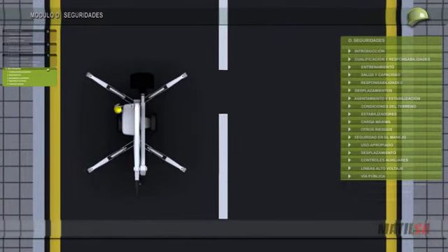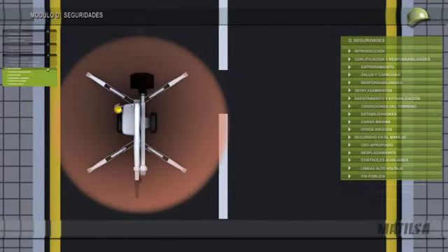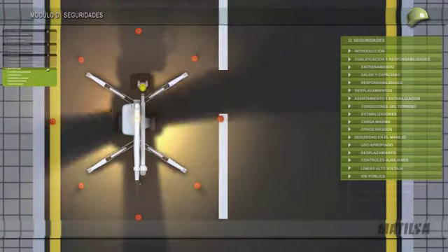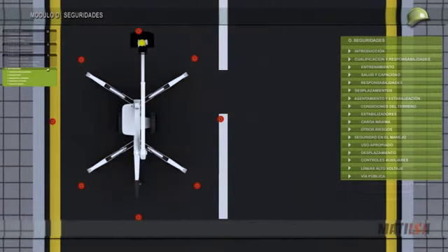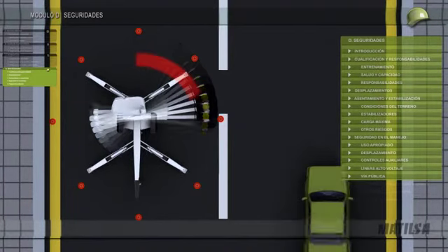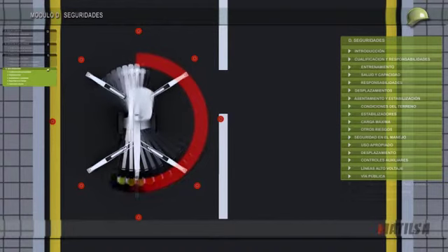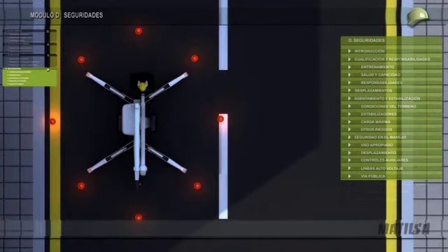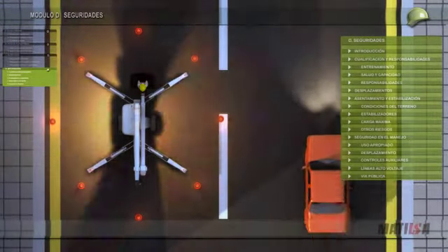Working on public roads. When working on public roads where other vehicles pass by, we should surround the working area with cones and visual signals. Besides these, it is compulsory to connect a rotating light onto the vehicle. It is very important on articulated platforms to be careful that the arms do not go over the area signalled by the cones, as this risks the platform hitting or being hit by other vehicles driving on that road. If we work in places where visibility is not good or out of direct sunlight, we should use light signals to indicate the danger.